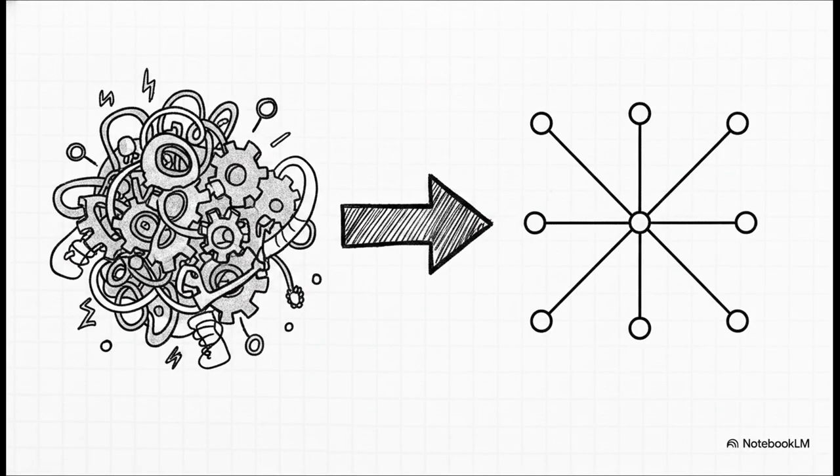And this brilliantly illustrates the true elegance of the per-unit system. We started off with a chaotic multi-voltage mess with raw values scattered everywhere. But by applying this system, we unified it. We've normalized all our equipment onto a common mathematical base, whether it's sitting on an 11 kV distribution feeder or a 765 kV transmission line. We identified that dreaded change of base trap, and we learned the exact formula to avoid it. Your grid is now a beautifully clean, normalized mathematical canvas, perfectly prepped for the next phase of analysis.